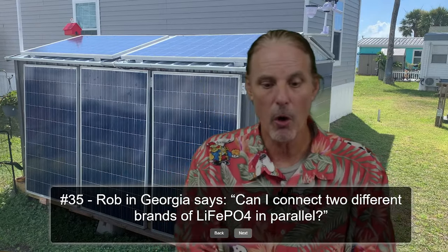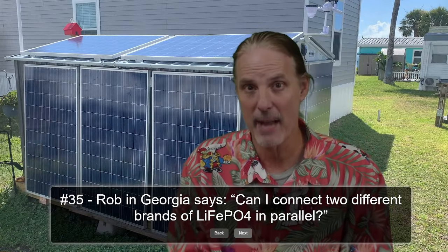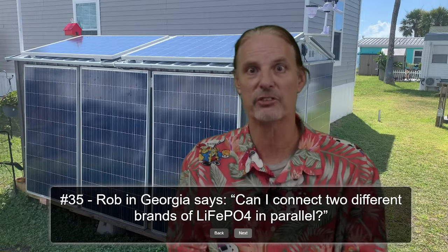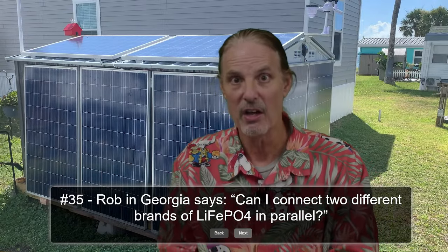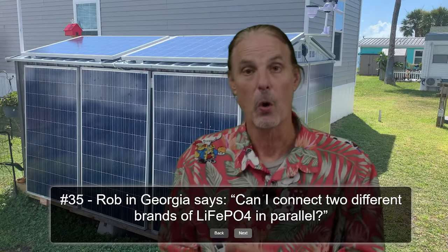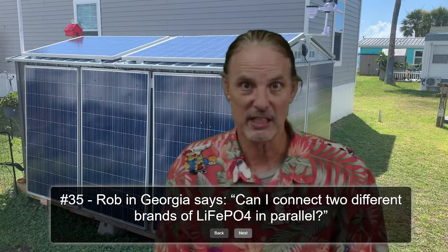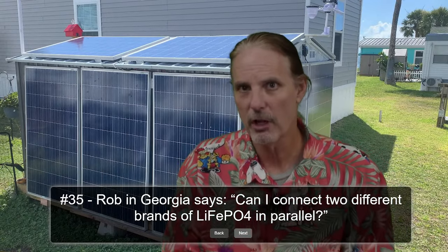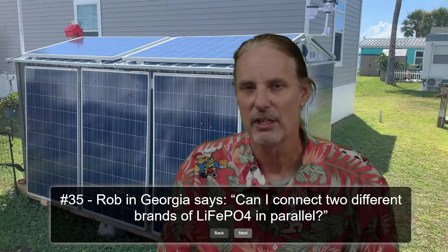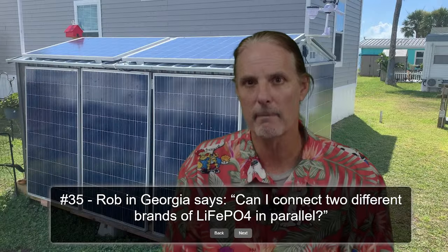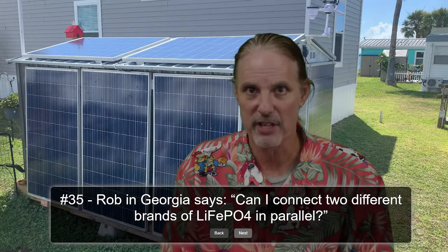They need to all be consistent batteries. In other words, they need to all be either lithium iron phosphate, 16-cell, nominal voltage 51.2 volts, or they need to all be 15-cell lithium iron phosphate batteries. So as long as you follow all those rules, yes, you can safely do it, but you have to do the homework and make sure that you have the right setup.